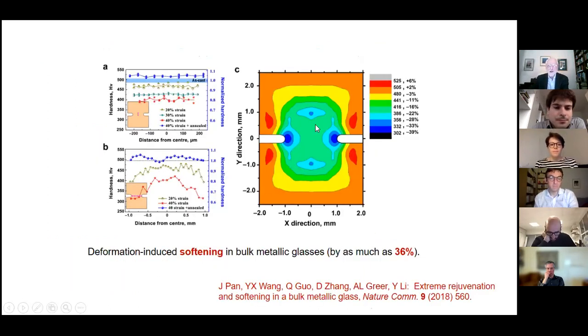When you measure, in this cross section of the notched cylinder, the hardness, as expected, the hardness goes down. So this is a system that has been rejuvenated. It goes down a lot, by as much as 36% reduction in the hardness. What we did not expect, which was perhaps rather stupid, was how much of the material would be rejuvenated. We expected a sort of coin-shaped volume here in the notch region, but no, it extends up and down considerably. The total dimension here is 4 millimeters across. And remember this is a cylinder, so roughly speaking, this blue-green zone is its own little cylinder of reduced hardness.